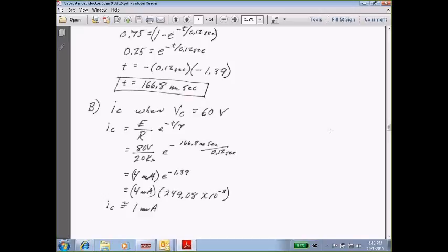And we can do that up to a certain point with static capacitors, just plain old, big old heavy capacitor banks. But then once it gets to where that's not feasible, then we would use a synchronous capacitor, or a synchronous, it actually looks like a motor. In fact, it is a motor, but it puts out a capacitive reactance rather than inductive reactance on the line at the same time of the same value so that they cancel out back to unity power factor.